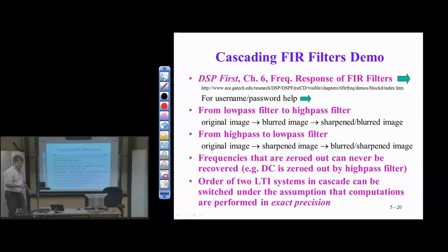So for the first order difference filter, we're going to need a 9-bit value to store the intermediate result by filtering along the rows. We'll then filter that 9-bit image along the columns. We'll need a 10-bit value to store exactly the computations. For the averaging filter, it's a little more complicated. We're adding 5 numbers together to produce a particular output value.